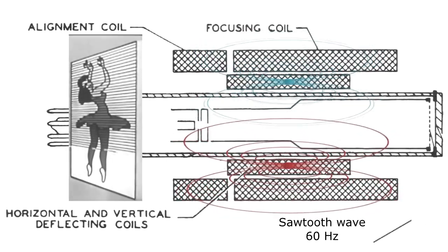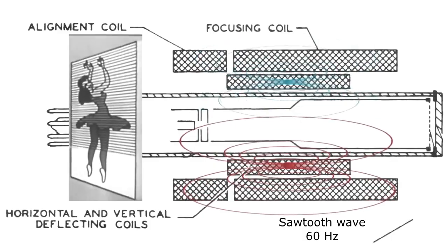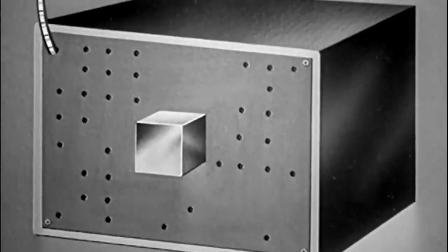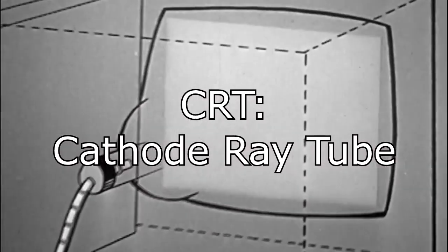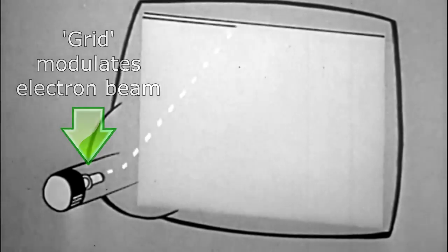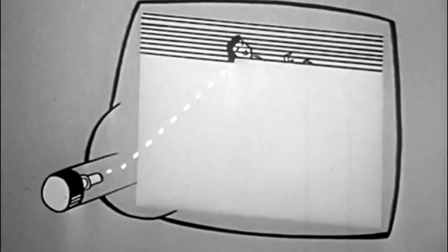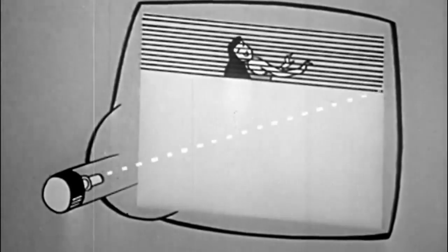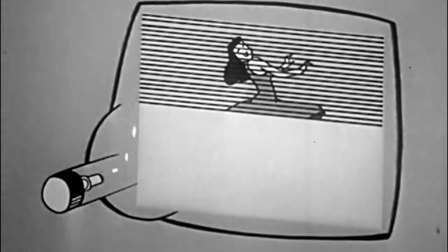V blanking summary. Repeated vertical blanking pulses at 60 Hz are inserted for each vertical scanning field to blank the retrace. The V blanking pulse width is 0.0833, sufficient time for the complete blanking of 21 horizontal lines in each field. The serrated V alignment pulse is also repeated at 60 Hz to align the vertical scanning in each field. The width of each V alignment pulse is 6 half lines or 3 complete H lines. The V alignment pulses are made much larger than the H alignment pulses so that they can be separated in the alignment circuits of the receiver.